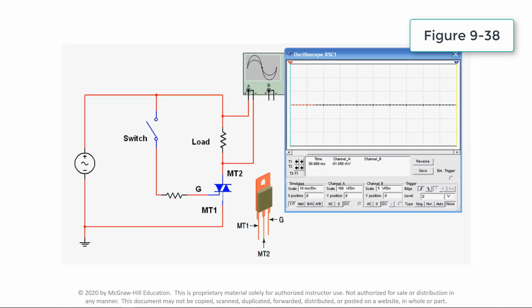When the switch is closed, a small control current will trigger the triac into conduction. The gate limits the gate current to a small control current value. When the switch is then opened, the triac turns off when the AC supply voltage and holding current drop to zero or reverse polarity. In this way, large currents can be controlled with a small switch, because the switch will have to handle only a small control current needed to turn on the triac.